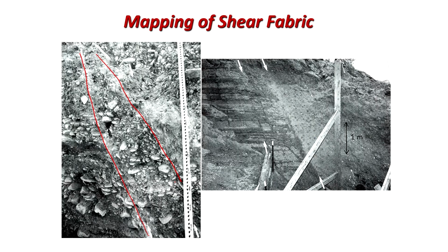And here also, if you see carefully, you have many such contacts which you can easily pick up and talk about the fault, because on either side the pattern of sedimentary units or structures is different. So here of course you can see this as micro faulting, what we call, but this is a major fault.